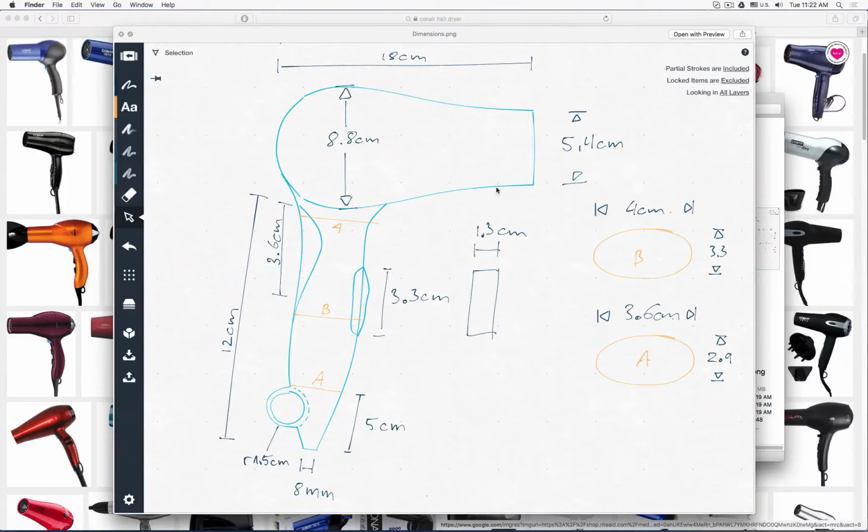I tried to measure. The top part is pretty simple because it's a very cylindrical element. There's a fan inside. Fans have to be round so they run smooth, otherwise it doesn't work. So this can be later created with a revolve command or so. But the handle can be very organic, and working there with revolve will be difficult. So we will sculpt this one more. So you see here I tried to measure the A, B, and A position, kind of like an estimate. And this doesn't have to be very precise when you start reworking on a product.